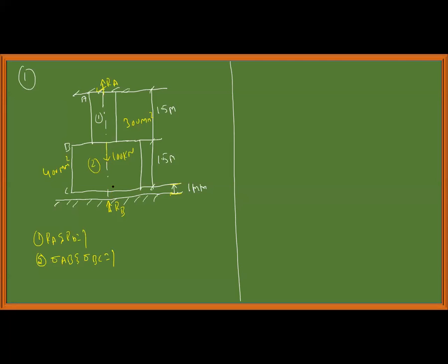Are you able to understand this? Let me repeat again. When I apply a load at this point B, the part AB is subjected to stresses and undergoes deformation, whereas the part BC is like a rigid body. Due to the deformation of AB, BC moves like a rigid body without any deformation. Up to what point?